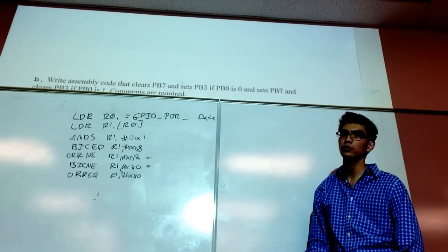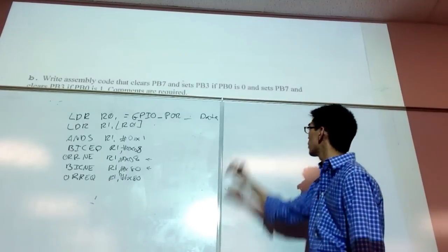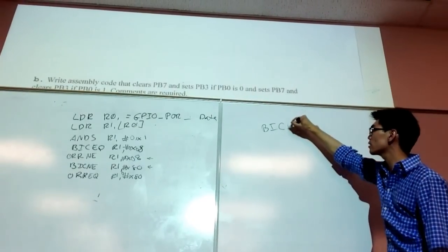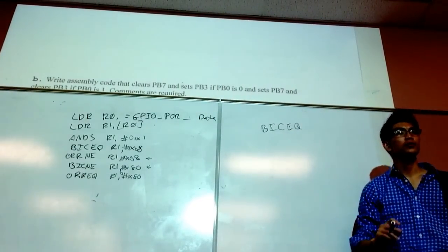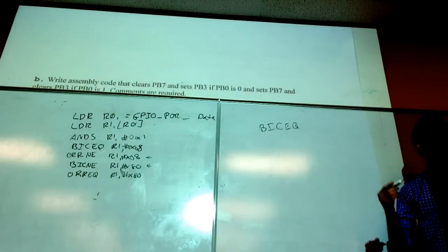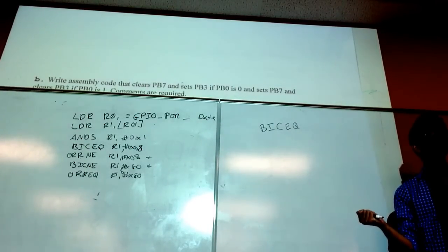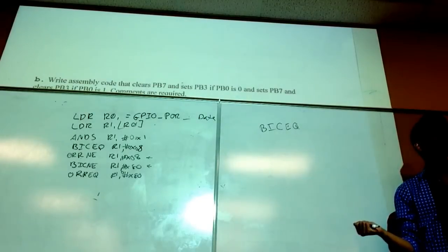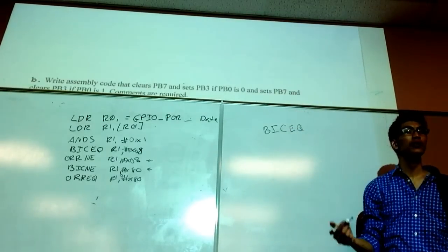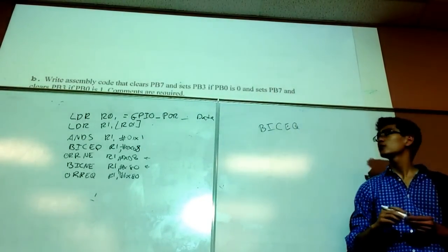So you guys should know this by now. Whenever I have an instruction, if I have any opcode, I can append conditional operators. This is in that chapter in your book. That instruction will execute or not execute based on the condition code flags. So this works sort of the same way as a branch. The branch instruction is basically a branch with these appended.